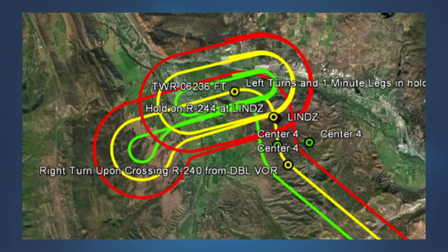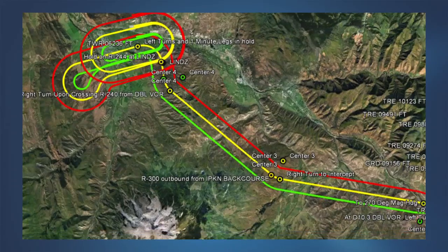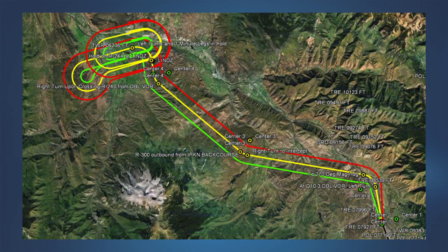The airplane's flight track can be accurately predicted based on the actual speed flown following an engine failure, for example V2 speed. Therefore, as we have seen, the area in which the obstacles that must be assessed for net takeoff flight path clearance is smaller than the area used for normal IFR departures.